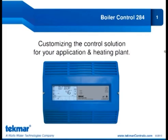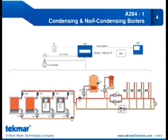Now, if you look at the 284, we call them, of course, the boiler pumps. All within the boiler, we have full control of the boiler pumps. Then we have sensors attached in the boiler loop piping, such as the boiler outlet sensor and boiler inlet sensor. We'll show you here, on this application drawn here, the actual boiler loop. We call that now the boiler loop. So the boiler pumps P3 through P6, plus the respective optional outlet sensors, S6 through S9, then the inlet sensor. That whole loop is the near boiler piping.